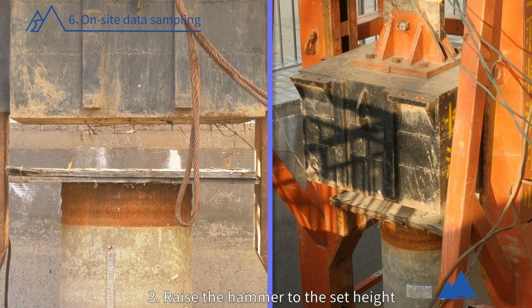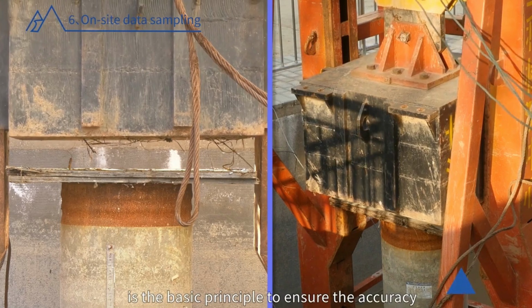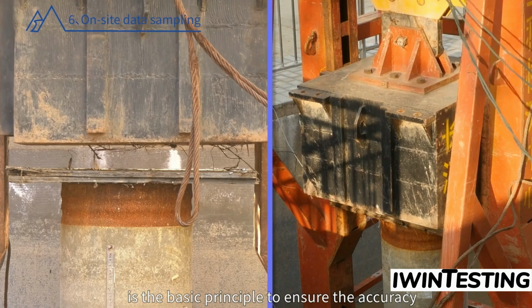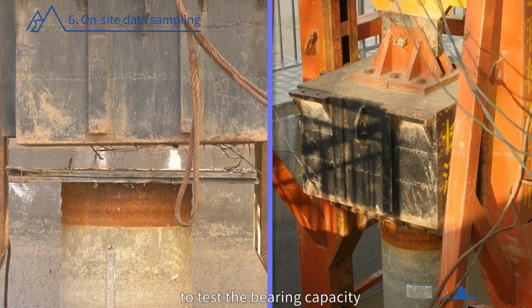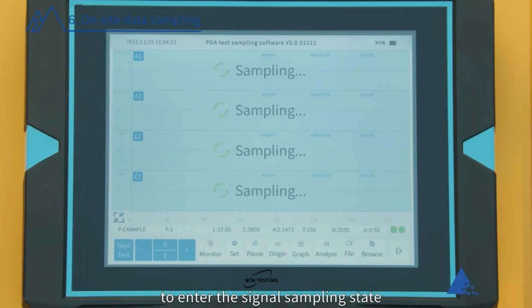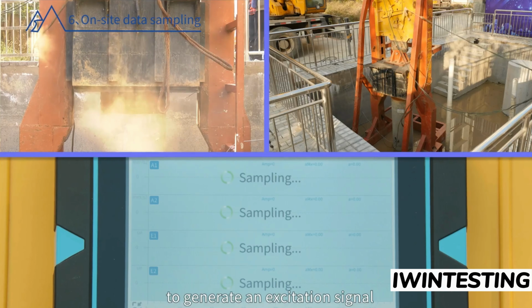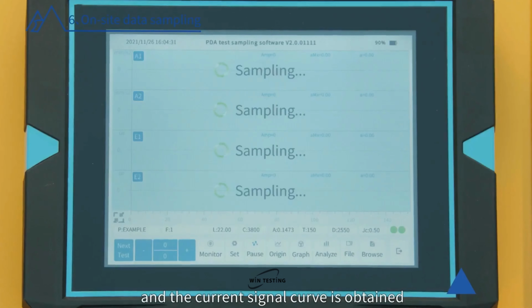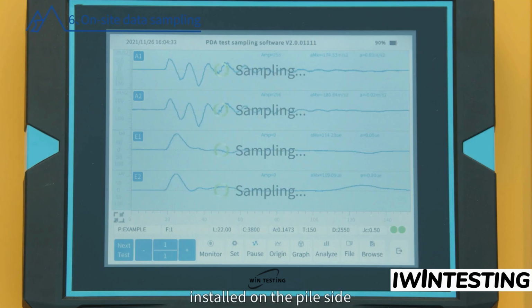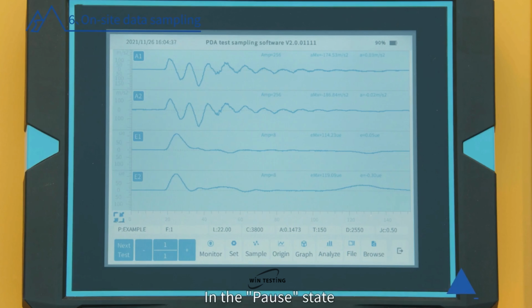3. Raise the hammer to the set height. Note that the low impact of the heavy hammer is the basic principle to ensure the accuracy of the high strain method to test the bearing capacity. Click Sample to enter the signal sampling state. The heavy hammer hits the pile head to generate an excitation signal, and the current signal curve is obtained through the sensor installed on the pile side. Click Pause to pause the sampling status.